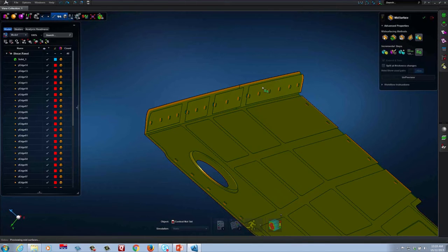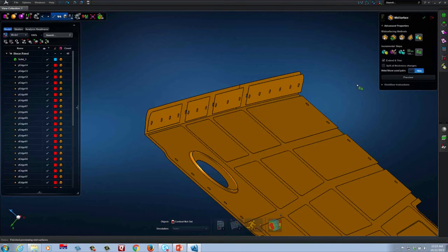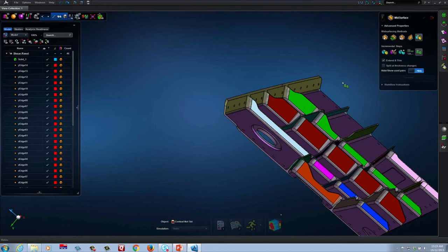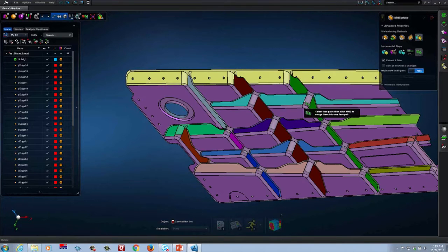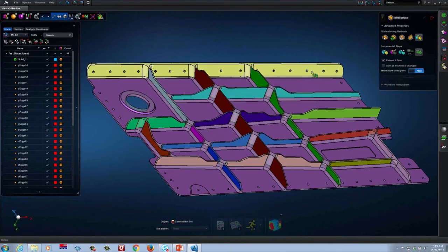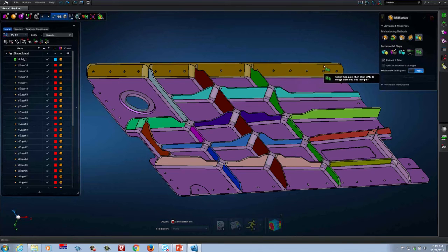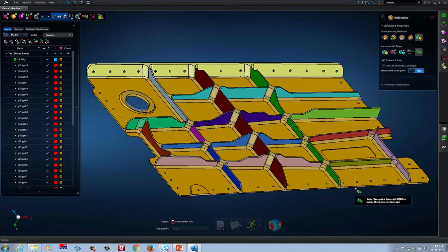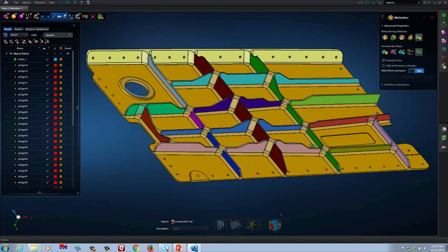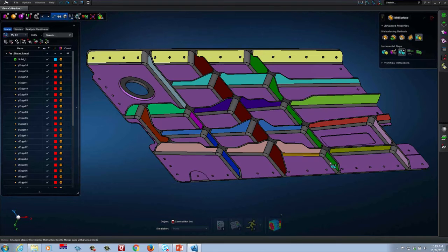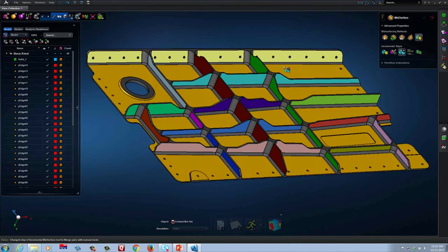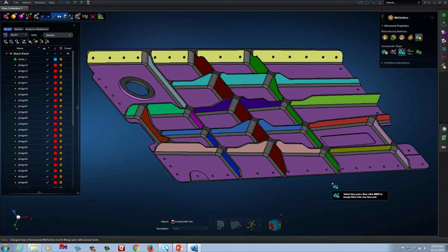So we can see that we've got a continuous mid-surface along this flange. We can see that it's down the middle, which was my engineering intent. Very happy with that. Going to unpreview that. So let's complete our work now. We saw that it was a good idea to have a continuous face pair to get a continuous mid-surface for that flange. Well, if you recall, I had these other areas here. I had this area. I had this area over here. There's actually another area up in there as well where I have misalignment, okay?